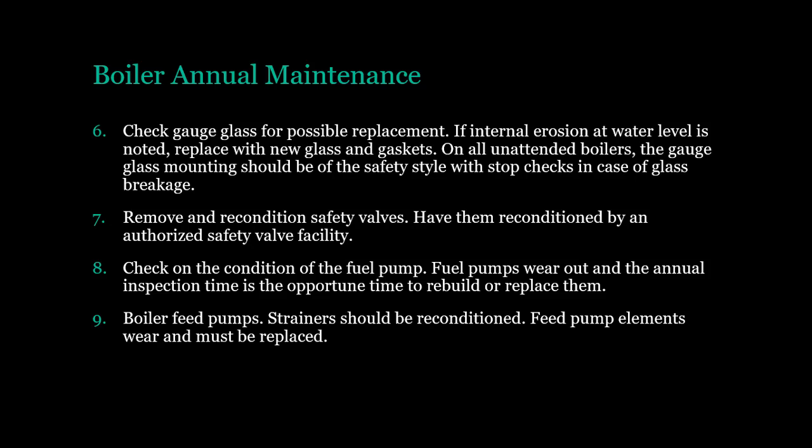Have them reconditioned by an authorized safety valve facility. Check on the condition of the fuel pump. Fuel pumps wear out and the annual inspection time is the opportune time to rebuild or replace them. Boiler feed pumps. Strainers should be reconditioned. Feed pump elements wear and must be replaced.